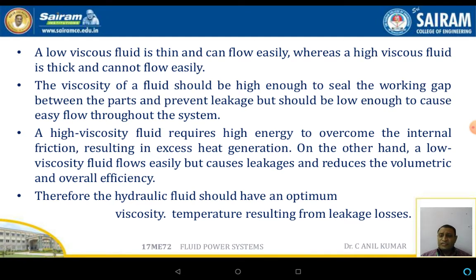The viscosity of the fluid should be high enough to seal the working gap between the parts and prevent leakages, but low enough to flow easily throughout the system. The high viscosity fluid requires high energy to overcome the internal friction, resulting in excess heat generation.